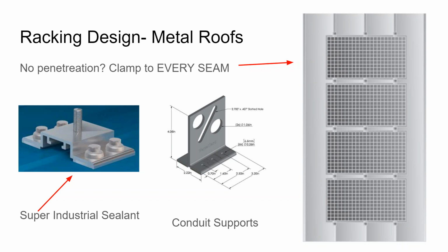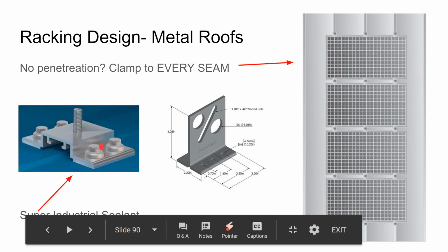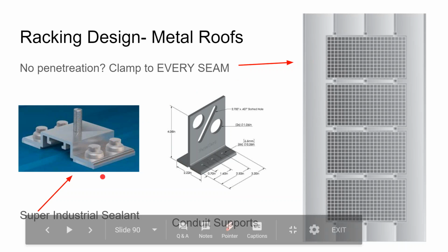And you're covering up the roof anyway. So, I know standing seam is considered to be higher end than rolled metal, but rolled metal is actually better for solar because you're lag screwing into and through the roof, which kind of terrifies the homeowner.